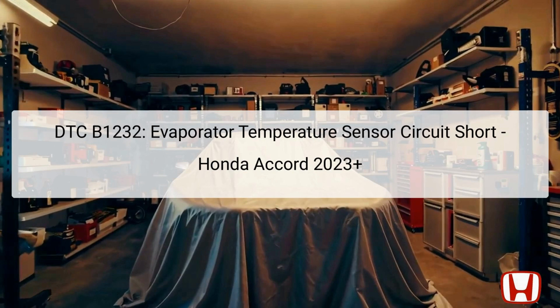The Diagnostic Trouble Code, DTC B1232, often referenced as DTC Indicator 0A, signifies a short in the evaporator temperature sensor circuit in the 2023 Honda Accord. The evaporator temperature sensor plays a vital role in the climate control system by measuring the temperature of the evaporator to ensure optimal vehicle cabin comfort.